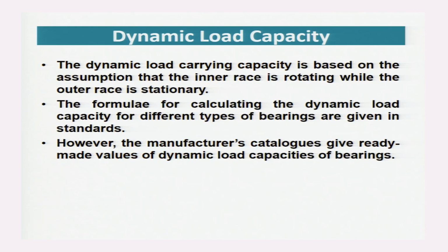The dynamic load carrying capacity is based on the assumption that the inner race is rotating while the outer race is stationary. The formulae for calculating the dynamic load capacity for different types of bearings are given in the standards. However, the manufacturer's catalogs give ready-made values of dynamic load capacities of bearings.